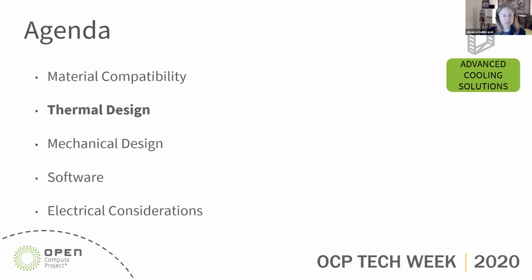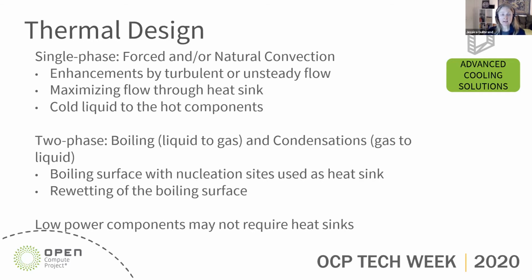Okay, so let's move on to the second topic here, thermal design. So again, traditionally used air cooling, we know how that works, but what is different when we're dealing with immersion? If we're starting off with single phase first, we can have either forced and/or natural convection. Really, forced flow is if you have a pump forcing the liquid or the fluid.